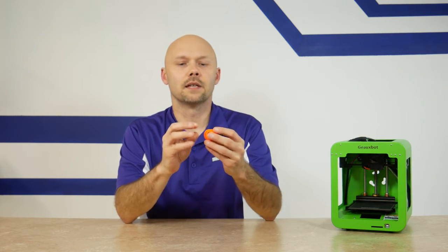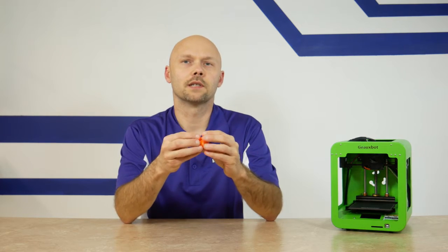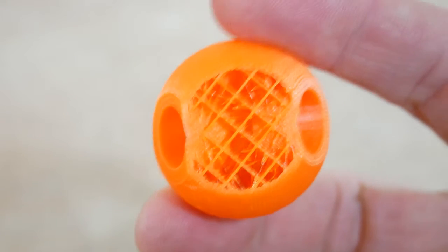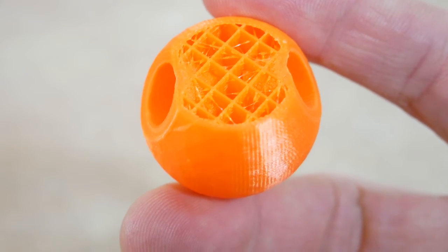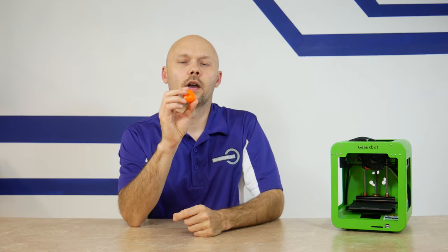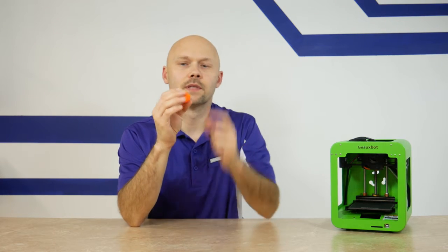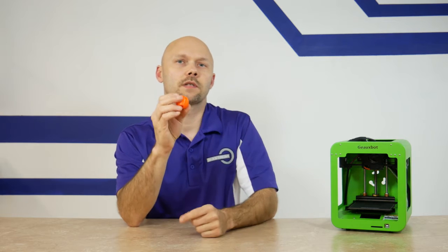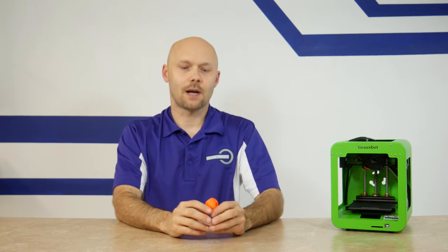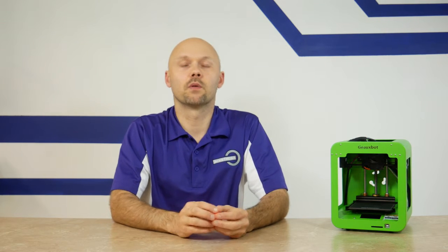Infill is the density inside the 3D model itself. Now as you can see here, this is a molecule ball that was not finished. I cut it off so you can see inside of the 3D print. Now a 3D printer can print from 0 to 100% filled. That means completely hollow to 100% filled. Most 3D printable objects are in the range of 20 to 40%. I typically go from 20 to 25, but it depends on what you're trying to do.